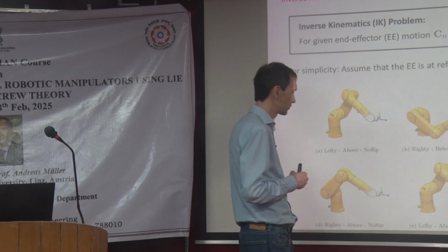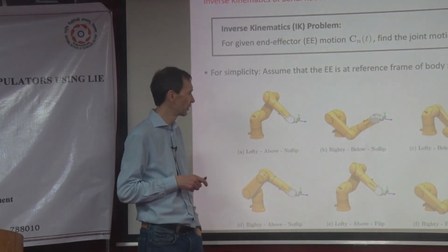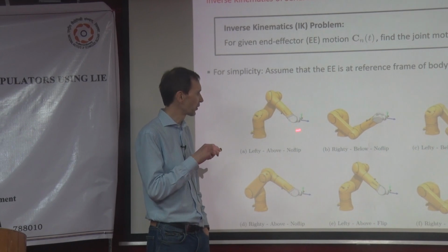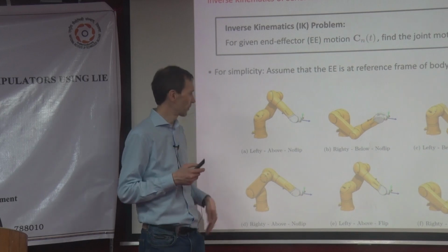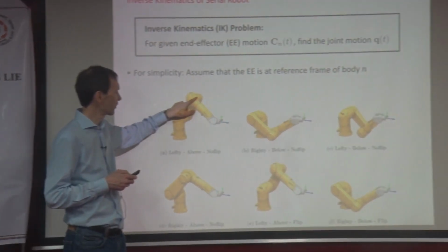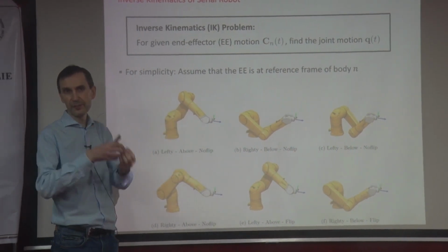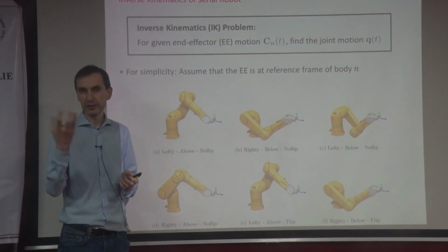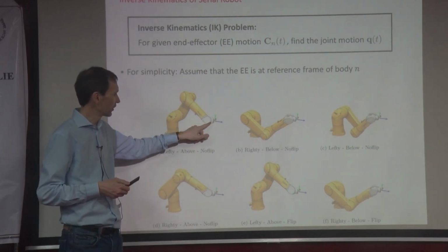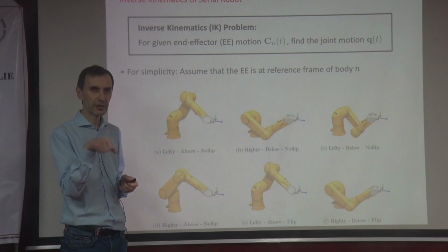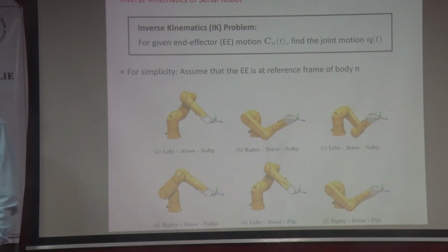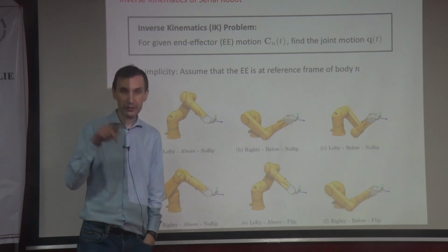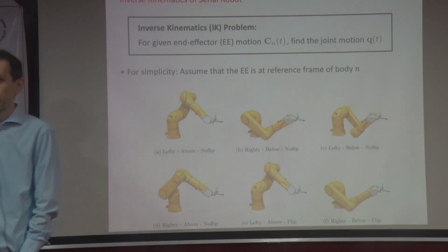There was one important result some time ago for this again, for these robots. I mentioned this one again: we have three joints that do the positioning, and then you have what they call the wrist, like the human wrist, because the last three joints just do the orientation motion. For this system, there is a closed form solution for the inverse kinematics. But I have to say it's more like a closed form solution algorithm, because there are some ifs and thens in there. But anyway, it's there.